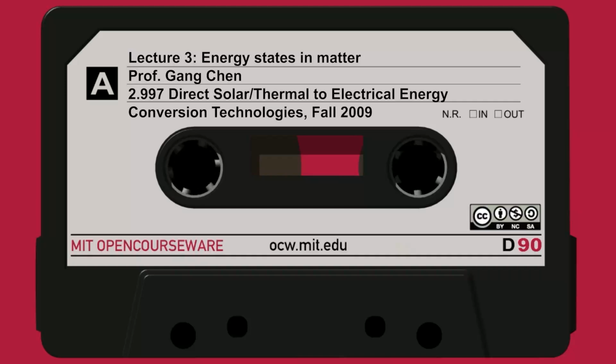And the Thomson effect is when we have a uniform conductor or semiconductor with a temperature difference imposed on it and a flow of current through it. Then along the material there is a distributed cooling or heating that happens. And this is because really at each section of the material, because of the temperature difference, the electrons carry different amounts of heat. So that's the Thomson effect.